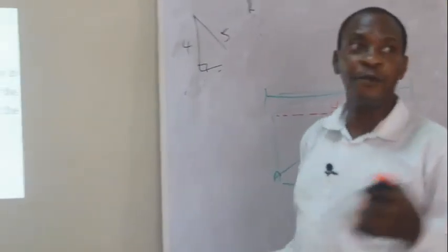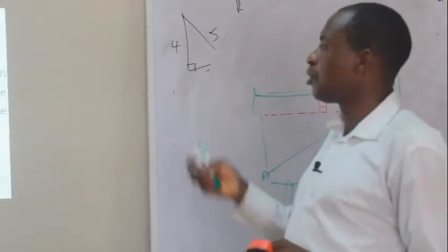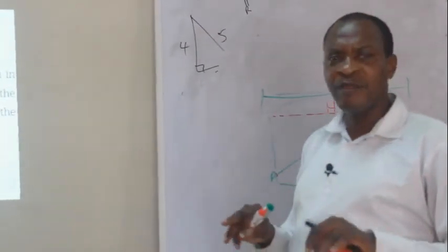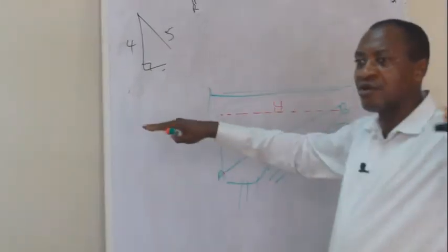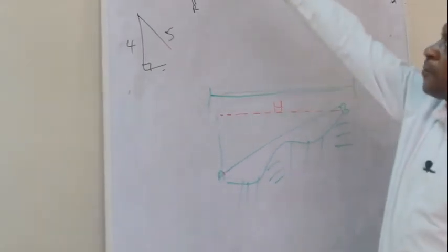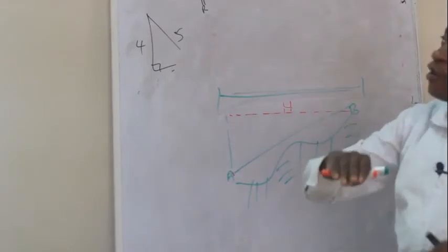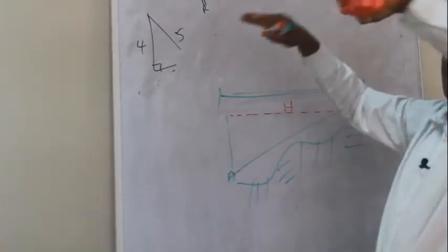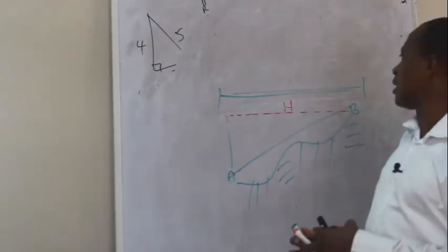And to you people in architecture or building and all that, please take note of this. Whenever you are measuring, we are measuring on a horizontal plane. Even when one plane is up and the other one is down, you have to ensure that you convert what you have measured to truly horizontal length.